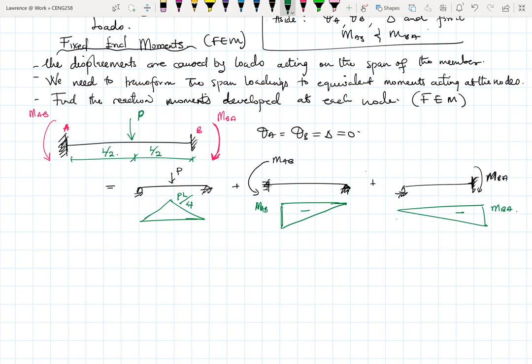All right. So they are combined into the M over EI diagram. In a conjugate beam, since our beam had fixed supports, it will be a free end. All right. So we'll end up with these diagrams. So this is PL. We have this one on the left side. Let me use a different color.